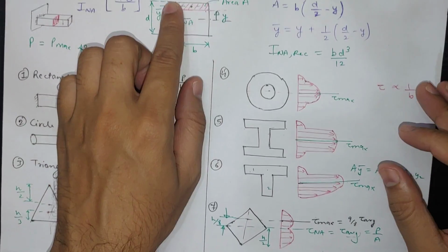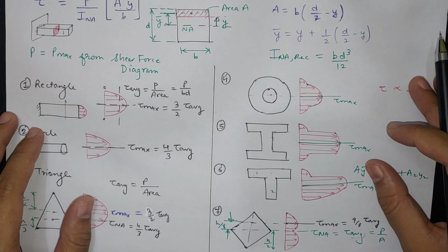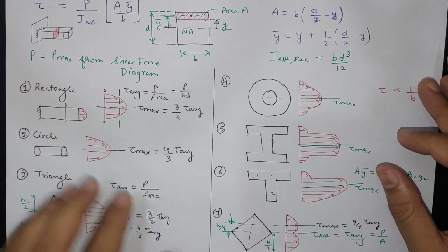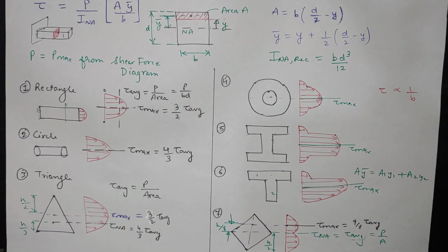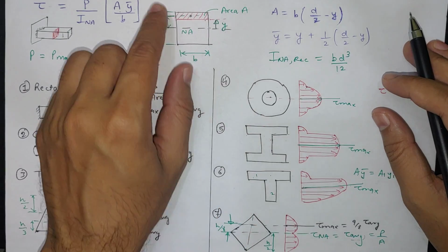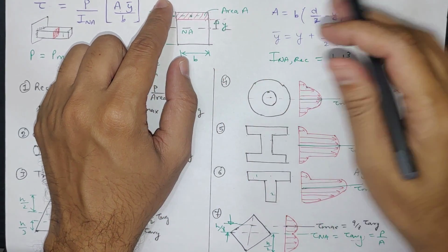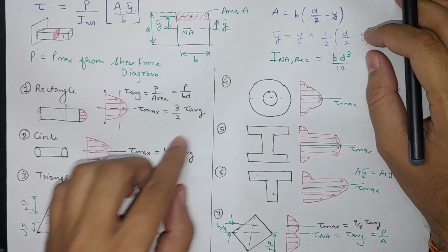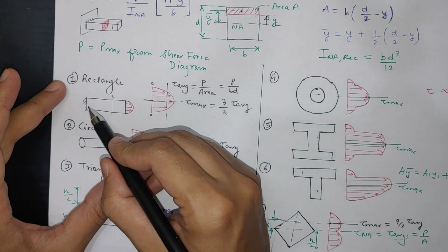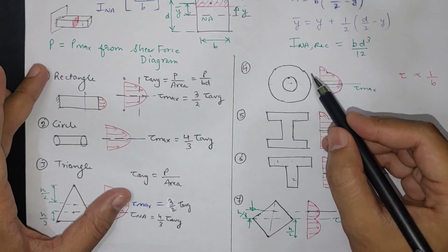This shear stress is sometimes asked in examinations, and it is a unique concept which is different from SFD and BMD. This shear stress is often neglected because it is much lesser than bending stress, and the beams are designed for bending moment. But we have to check shear for various beams, to make sure that the beams do not fail in shear failure. And this shear stress will fail the beam in the lateral direction because tau maximum occurs at the central line.